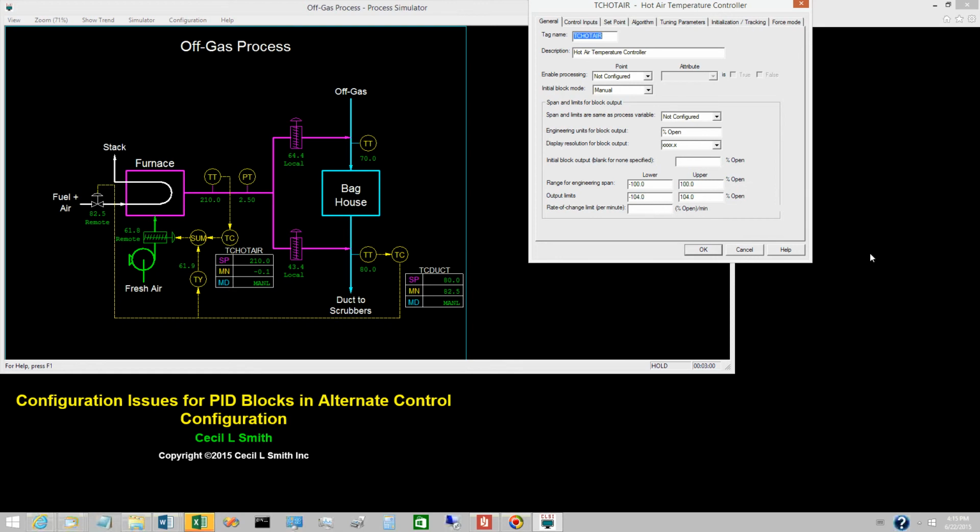The most convenient approach to implementing control configurations that include characterization functions, summers, and the like is for the output of all PID controllers to be expressed in engineering units. When the output value pertains in any way to a final control element, the output range for the PID controller is preferably expressed in the engineering units percent open. Control configurations are easier to understand when implemented this way.